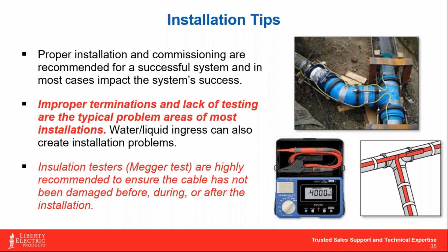And then before you spend a lot of money to insulate over the top of that pipe, we can address the issue, versus everything's on, you paid big money for ceramic insulation or something like that over the top of these pipes, you flip on your circuits and find out you got a fault on one of them, and it was due to, again, just the cable was damaged because it got pulled across a burr, something to that extent. So if the installer is measuring on a regular basis, he can easily uncover any sort of damage to that cable before we get too far down the line.